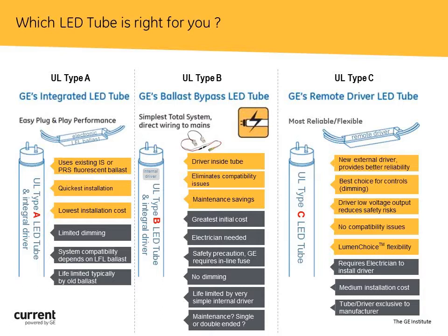Let me move back to Type C. Type C, no compatibility issues because you now have a dedicated remote driver with your brand new Type C LED tube. And then finally, GE's just introduced a family called Lumen Choice. Now, Lumen Choice is a really cool Type C alternative.